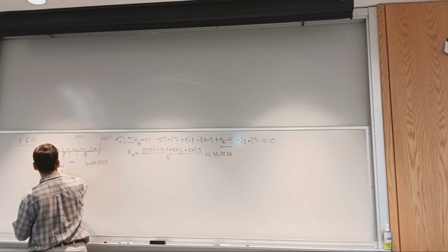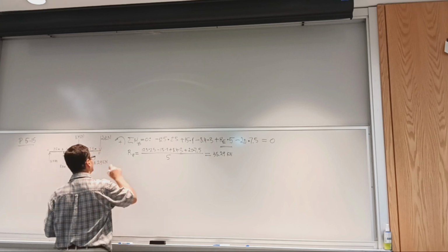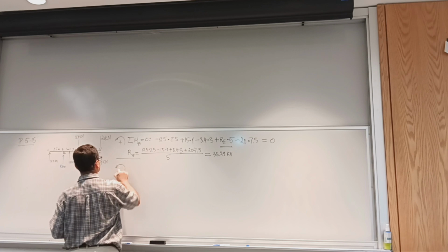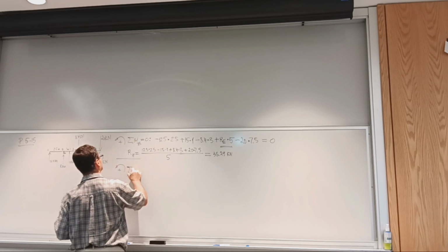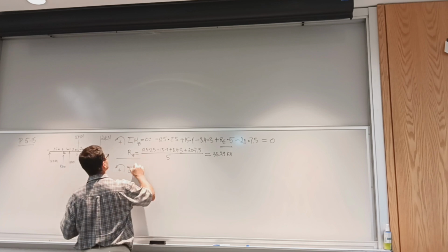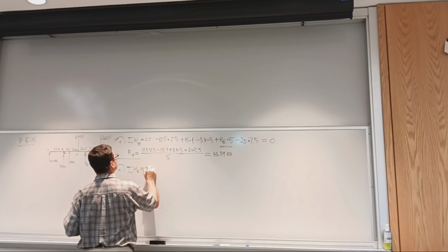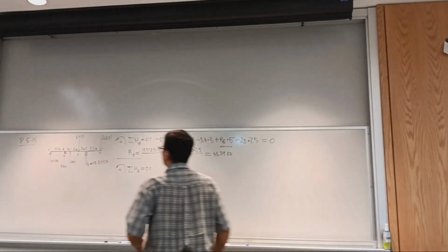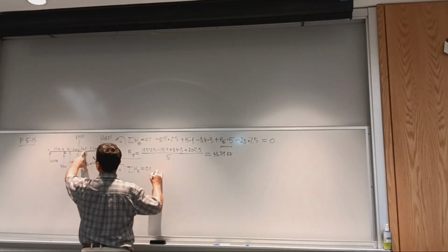Kilonewtons. Let's look, we have RB to take care of. And we're doing the same. Again, you don't jump ahead unless you're really confident. And you shouldn't jeopardize the rest of your calculations on not having the reactions correctly evaluated. So the sum of moments about point E now equals 0. So let's see what we have. So I put my finger at E and start to write moments.